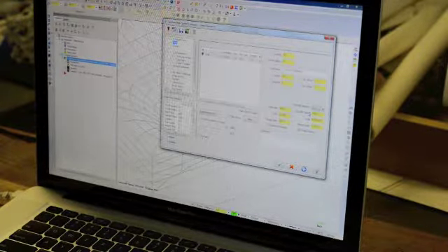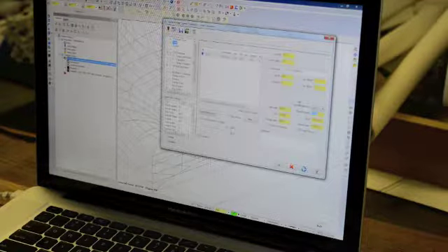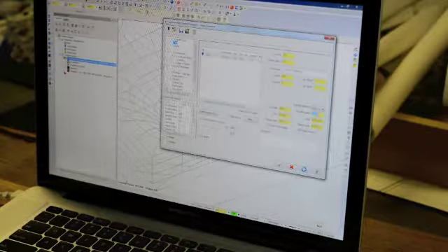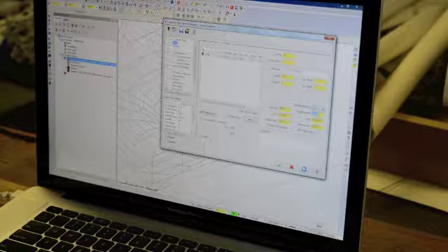And the spindle is always going to be clockwise. Now the spindle speed, there's actually a calculation we'll have to do, which is going to require the use of a chip load chart, and that's going to give us the spindle speed to use. It'll give you a precise number, but it's something you just have to tweak and experiment with based on how sharp your tool is and what the actual material is that you're cutting. So it gives you a close number to use, but not necessarily exact.